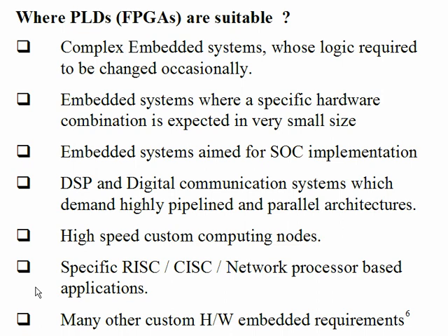Now, yeah, there is a difference. See, the point is, when you have a very small instruction set and each instruction takes a considerably small amount of time, the control to optimize the application is more in the hand of the programmer or the user. When I have a very refined instruction set, each instruction takes an exactly fixed amount of time and I have only 20-30 instructions, so the programmer has more responsibility and more possibility to fine tune the application and get the best performance out of it.